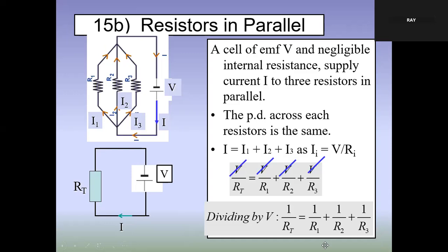1 over R, it's a parallel circuit arrangement. The PD across each resistor is the same, no? V. So you want to find I1, it's just V divided by R1. I2 is V divided by R2, because it's parallel. Parallel. Okay. Here we apply Kirchhoff's current law, this part.